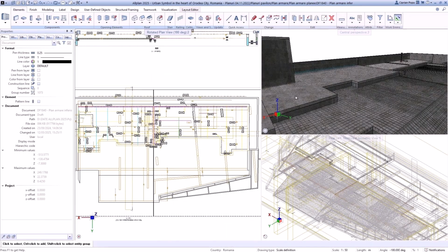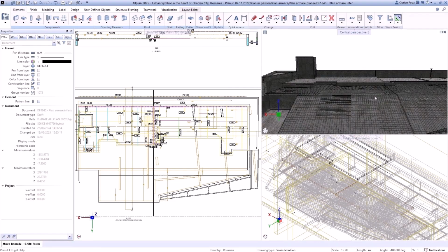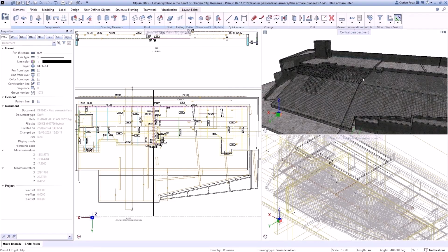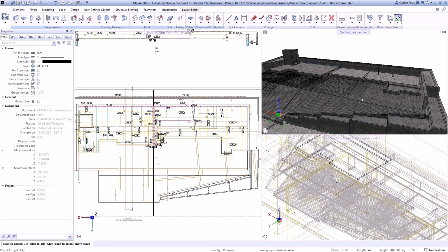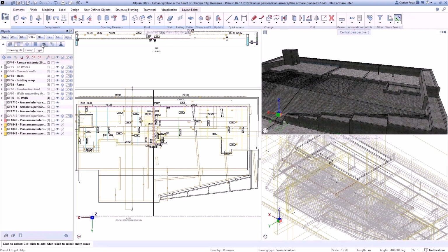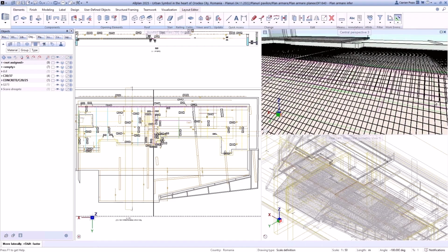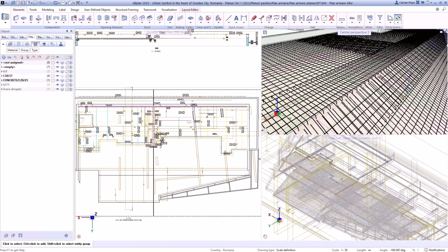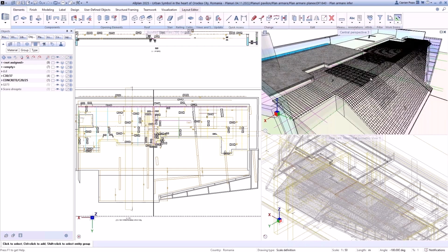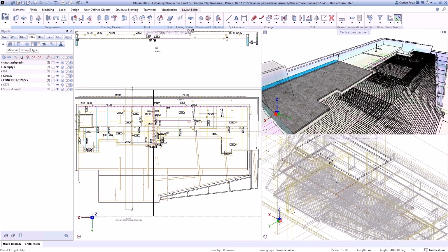So it's a very interactive way without the structure analysis engineer giving too many sketches and explanations of what the draftsman should do with those colored parts. So the draftsman just knows detailing rules and starts reinforcing until it gets white, of course, with the final approval from the one who did the calculation. But in the end, you have here the zones that require more reinforcement, and they were interactively done here.